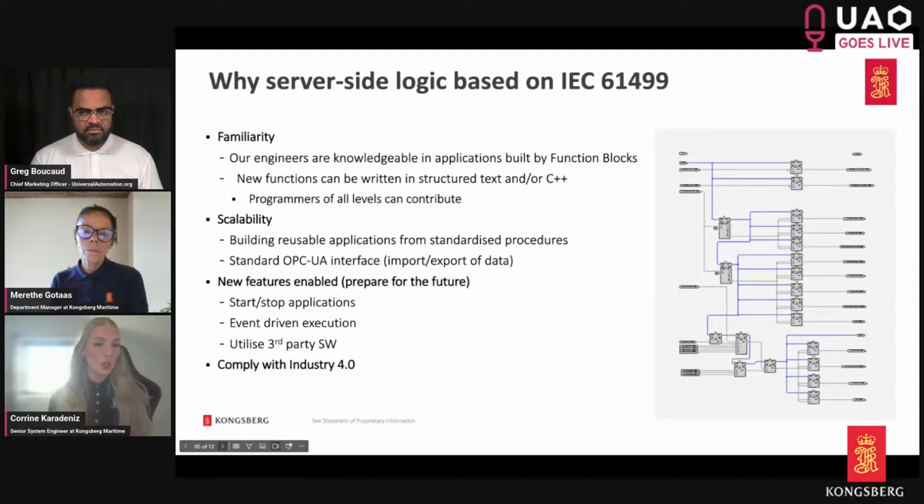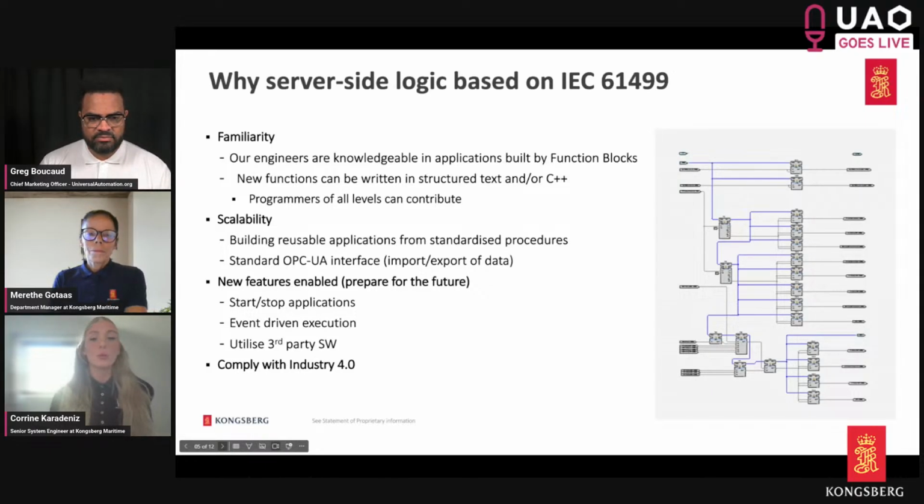So server-side logic in IEC 61499 is built up using function blocks. And our engineers are very familiar with function block applications. We can create new functions that can be written in structured text, as simple as structured text, or more complicated as C++. But it means that we can have programmers of all levels contribute to the process. And we've also found that it's a scalable solution because we can build reusable applications from standardized procedures, and we have a standard OPC UA interface for the import and export of data.